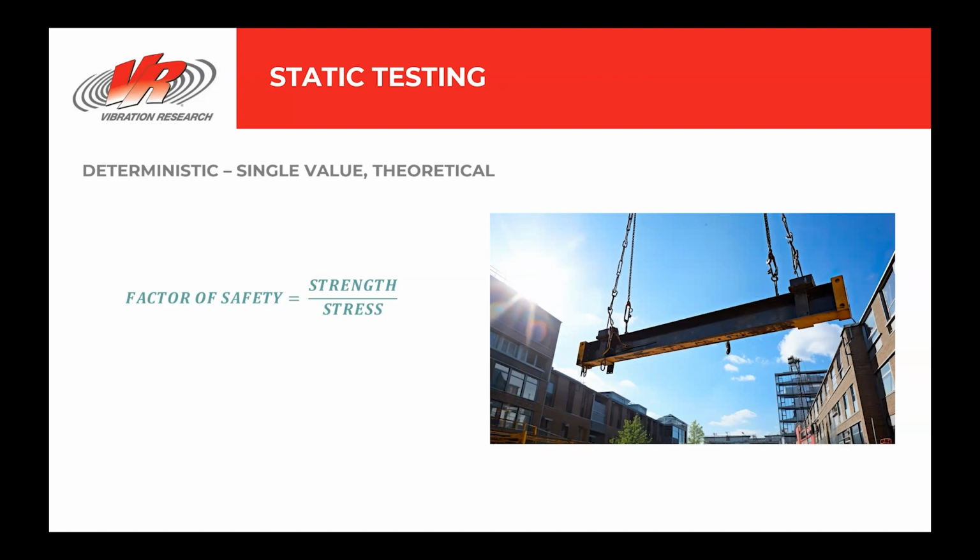Conventional engineering thinking, and what most of us probably learned in school, is that a designed-in factor of safety is a good measure of robustness against failure. This is true for situations that are essentially static, have very few parts, known loads, and use materials that have well-known SN curves. The factor of safety is single-valued, theoretical, yet practical and highly deterministic in nature. For those situations, the factor of safety concept as defined by material ultimate or yield strength divided by a known stress level is probably satisfactory.